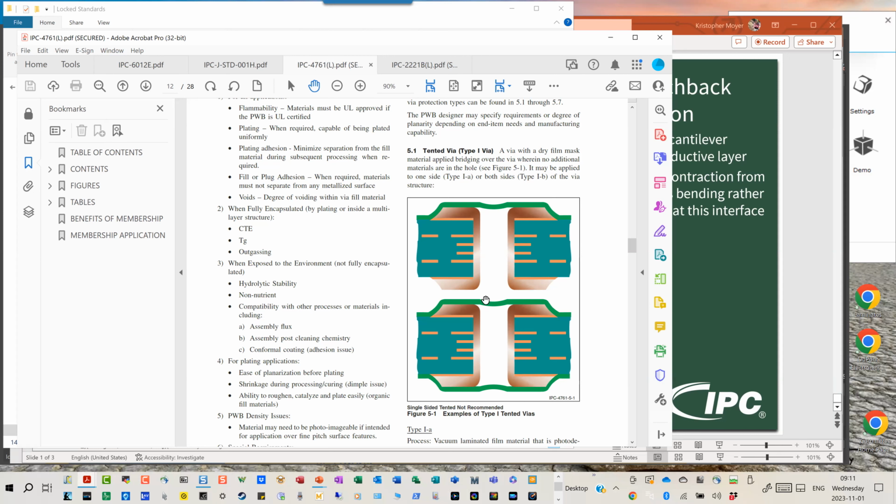In which case, now if this via barrel is underneath the component of the body, like an IC or a resistor or something of that nature, it's been known to do what we call the popcorn effect. Parts literally come popping off of the board before they're soldered into place because of this explosive decompression.